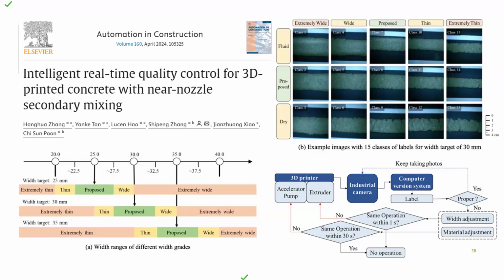It will be a bit more flowable or less. You can see in these figures that the width of the layer is fixed and then it is reducing, and here the width is more, here the width is cracking. So in actual construction, when you do the work, it can happen that the extrusion layer can have different rheology.